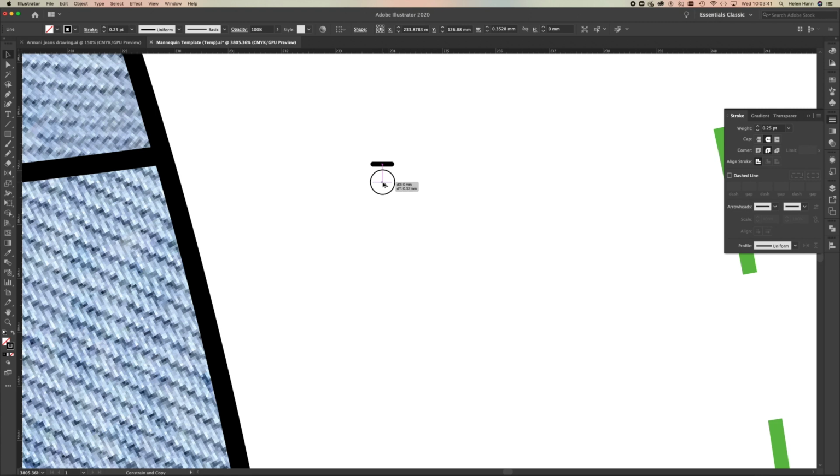and just make another one. Now how I did that, I'll just do that again because I didn't explain what I was doing. I'm just dragging this down, and as I'm dragging I hold the Alt key. Now when you hold the Alt key you'll notice that your cursor splits into two arrows. That's basically telling you that you're going to make a copy, and by holding the Shift key, at the moment I can move anywhere at all, but the minute I hold the Shift key you'll notice that the line is constrained to move either vertically or horizontally or at a 45-degree angle. Okay.